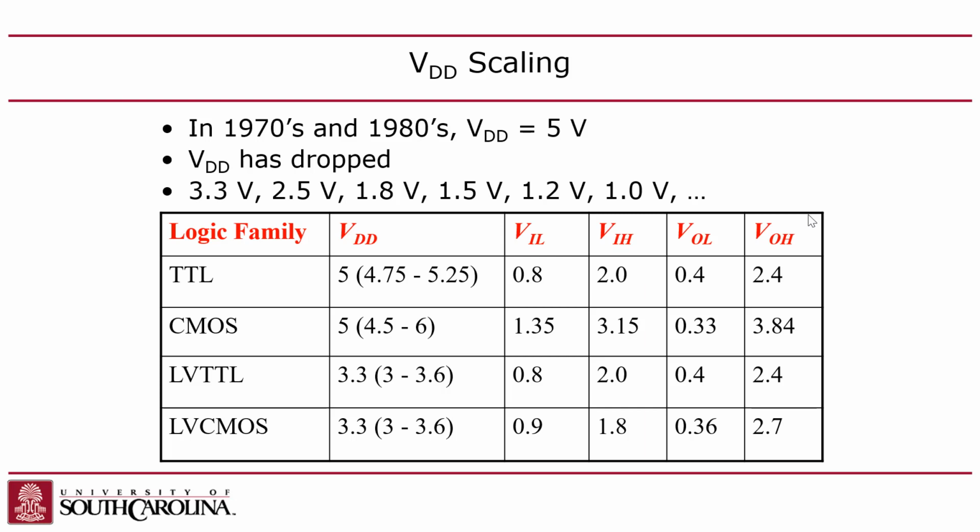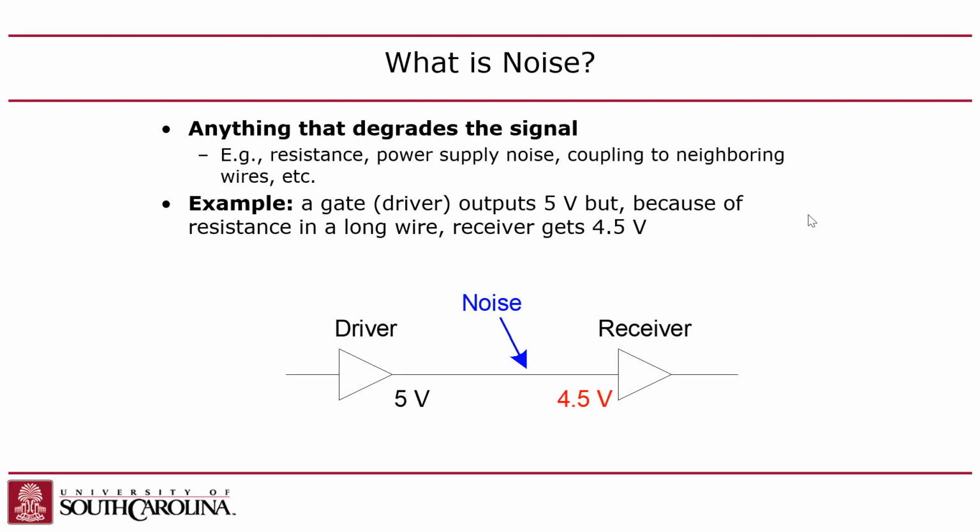Whenever you need to speed up your CPU, you increase the clock rate, but you also increase the supply voltage, right? So you do voltage and frequency scaling. But the lowest voltage you'll see could be 800 millivolts, something like that, and the highest you might see is maybe 1.2 these days. Part of that has been the advances in the fabrication technology and the device technology.